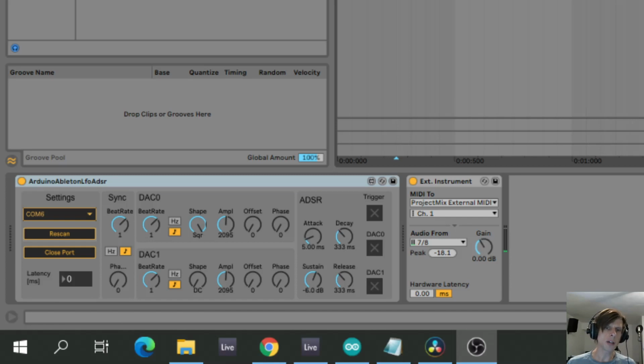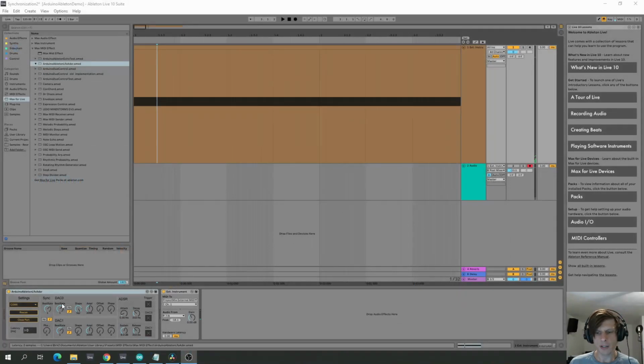So I'll show you now how to compensate for the hardware latency and how we deal with the LFO then later on. First, let's really only measure the hardware latency of the synthesizer itself. And of course, we want to then not have the LFO over-modulate, so I'll put the amplitude to 0 and just bypass basically the LFO.